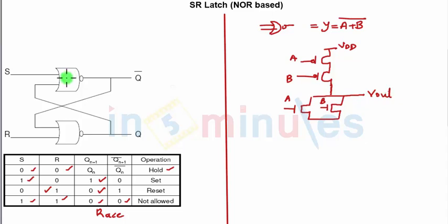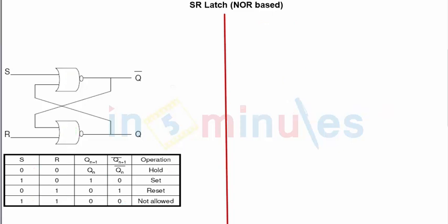Here we see that there are two NORs, NOR 1 and NOR 2, and we will be implementing both these NORs and making the connection, and that's nothing but the implementation of SR Latch in NOR style, or I could say implementation of SR Latch in static CMOS style using the concept of NORs. Okay, let's quickly do that. So let's make our two NOR circuits. As we said, this is NOR 1, this is NOR 2.